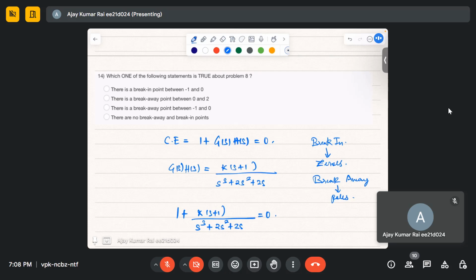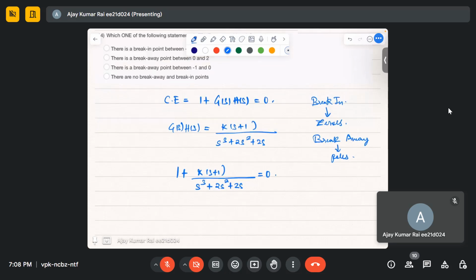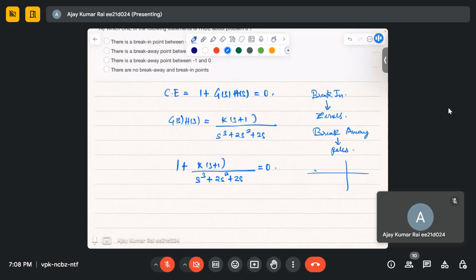They are going from the real axis to the complex plane, like in the conjugate plane, where it will have real and complex values. So like this, you have seen two poles exist, and the root locus is going like this. This point we will call the breakaway point. So these are poles, right?